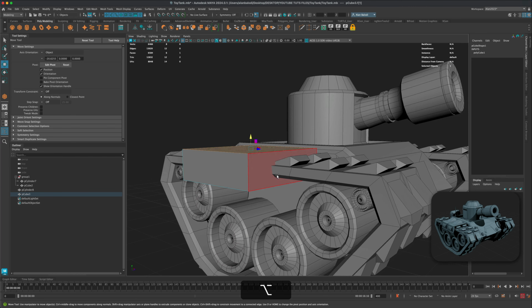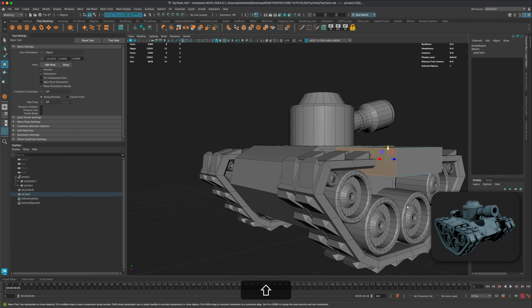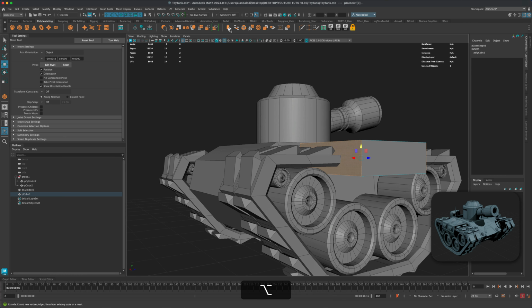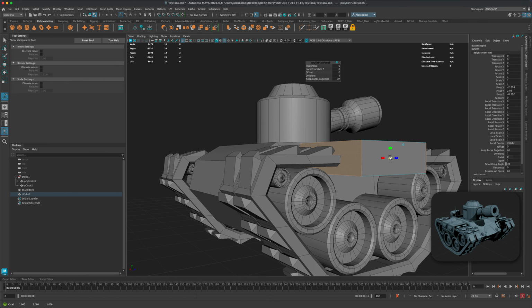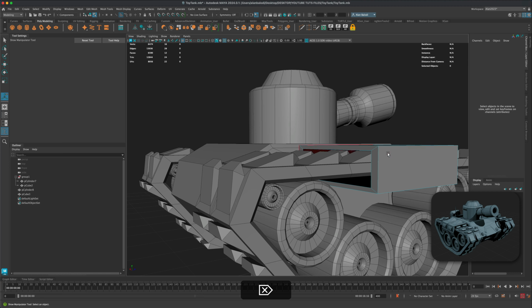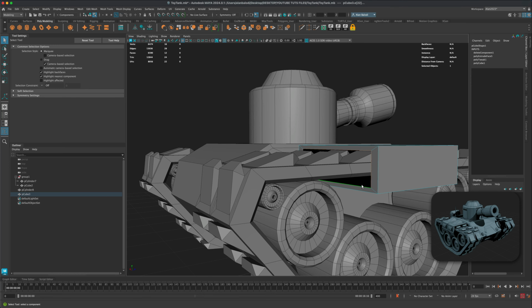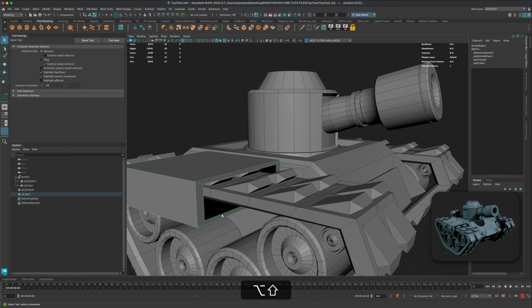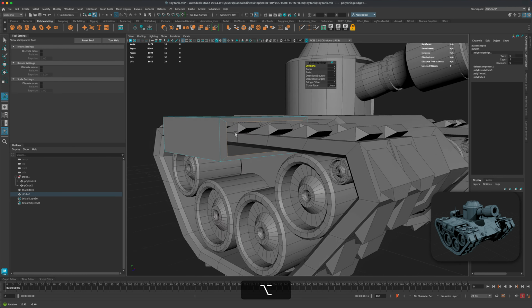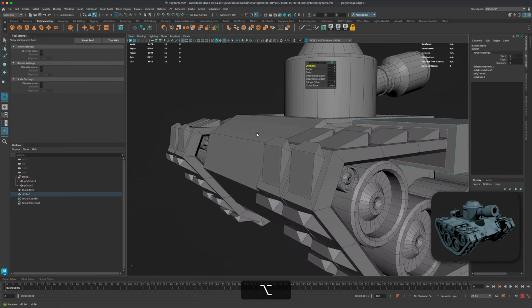So I'm going to, again, make sure that it goes a little bit over. And now what I would like to do is I'm going to punch a hole here and here. So I'm going to grab both of these faces, and let's do another extrude and just kind of do something like this. Just make sure that it's over the track, press delete key. Then I'm gonna select this edge here, hold the shift key, select this edge and do a bridge. And you can see what that did. It kind of connected both of those pieces together, right?